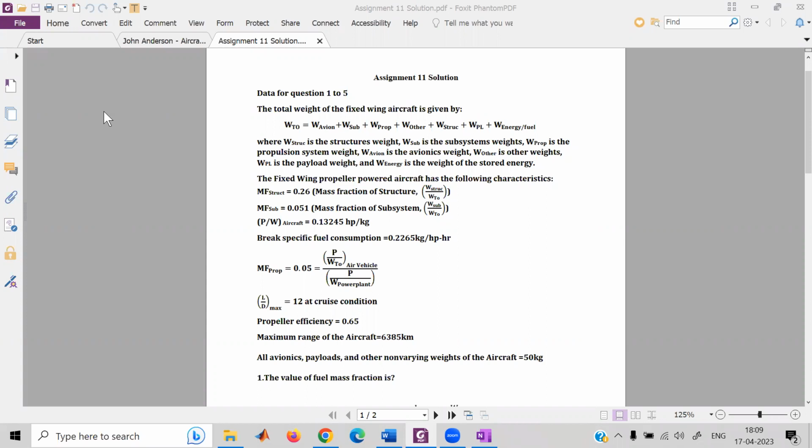Because in the last to last session that we had, we were designing an aircraft, and we had requirements similar to what we have right now. So we had range and other things also. So there is a philosophy. How do you estimate the total takeoff weight and fuel weight? So I just want to invoke those things here. Rather than solving a particular question, we want to build a philosophy of how to think about a design problem.